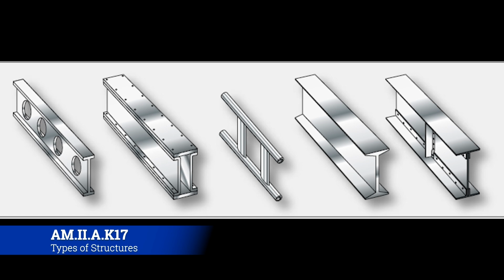The other ones you'll see in different places. The more robust, very structurally sound ones that you'll see off on the right are ones you'll see on heavy commercial aviation. So if you go and look inside of a 737 Max's structure, you're going to see that type of wing spar. Whereas if you look at a Cessna 172 or a Piper Cherokee or something really lightweight, you're definitely going to see more of the one on the far left. The other three in the middle you can find elsewhere. It really depends on what the aircraft is, what its mission is, what its wing design is, all those types of things. But those are different spar types.